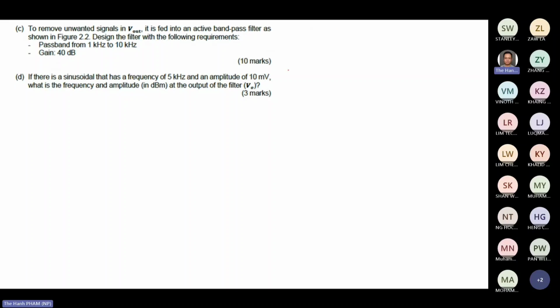These are a few things we have seen in our class. So if you think of the pass band, it is like this. For example, this is the max gain. If this is 40 dB, then the point 3 dB down should be 37.